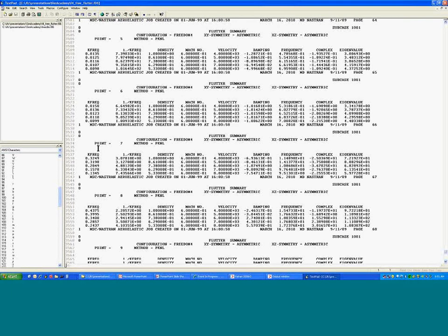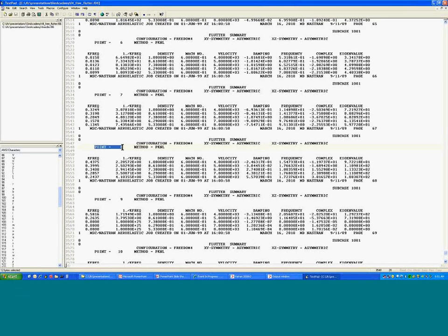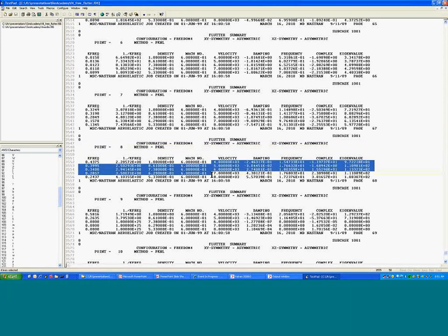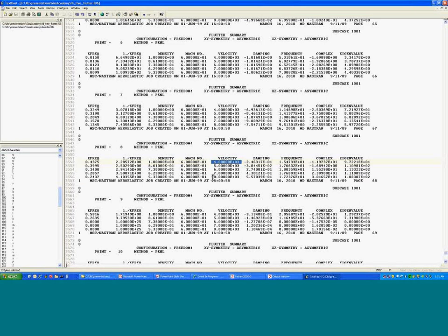It's not exact, but generally each point roughly corresponds to a particular mode in the system. In this case, this wasn't a complete flutter analysis, but I did a solution at 5 or 6 different velocities, ranging from 4,000 inches per second true airspeed up to 8,000 inches per second. We can see that the frequency of the 8th mode varied from about 15.4 hertz at 4,000 inches per second, and you can see it moving around a bit as we add aerodynamics.